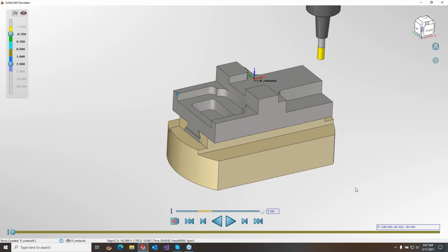If we pick a vertex, you can see down here in the bottom right, we get a measurement label or a measurement window. You can click, and this allows you to copy and paste any of the values. When I put my mouse over it, we have a little tooltip that tells us the data that we get. We get vector information, distance, length, points, angles, and distance to the target. So when we click on a point, we get the XYZ point. If we click on a line, we get the line. If we click on a face, we get the vector of the face and the distance to the origin and also the distance to the target.